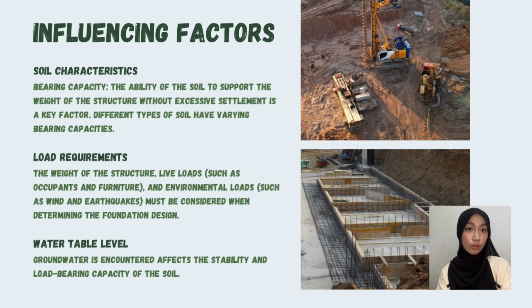Next is load requirements. So when designing a foundation, you need to think about the dead loads, live loads, and also environmental loads. Considering these loads helps keep the foundation strong and stable. Lastly is water table level. The level of groundwater can affect how strong the soil is. When the water table is high, it can make the soil weaker and impact the foundation's stability.